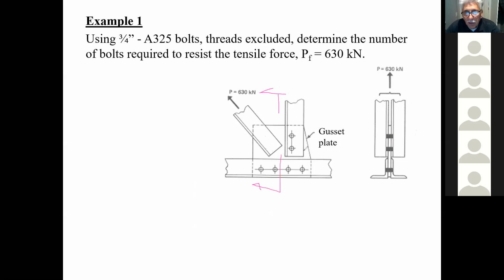If I'm looking this way, I see one angle, but on the other side I have two angles. So in other words, I have two angles here, one beside the other. And this is a gusset plate here that represents that thing here. And these are the two angles that form the bottom chord. So I hope you guys can relate to the cross section.